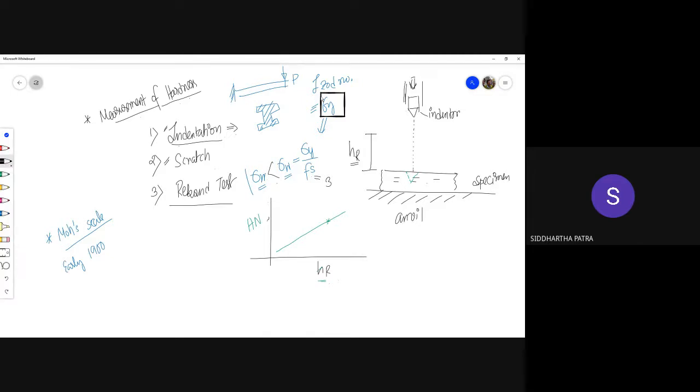The value of the toughness that you get from Izod number, if we consider that Izod number is a true measure of toughness, that we cannot comprehend unless, of course, we compare two materials. So even in the Izod test, we tested on two different materials. One was aluminum and the other one was brass. Today also, for each of the experiments that you do, we will be doing Rockwell Hardness Test and Brinell Hardness Test. For each case, we will be taking specimens of two different materials. So the hardness only makes sense when you compare two different materials.